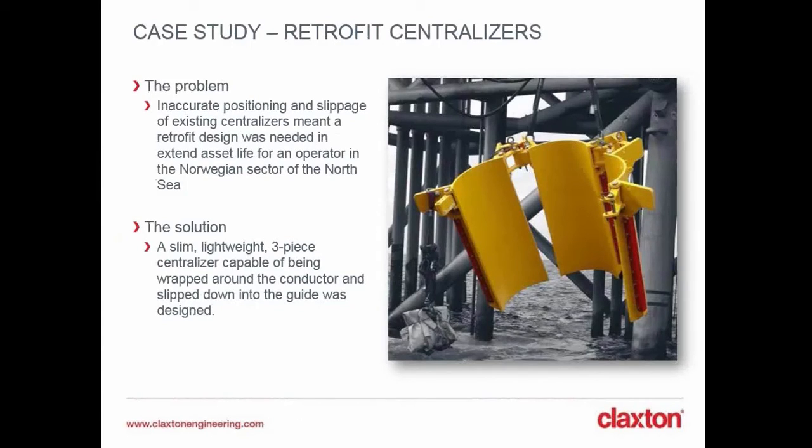New retrofit centralizers in this case were required given the inaccurate position of the original centralizers and a few other centralizers that have slipped from where they were originally fitted. The picture shows the retrofit centralizer in the open position, which allows it to be wrapped around the conductor, and then slipped down into the guide where the centralization is intended to sit.